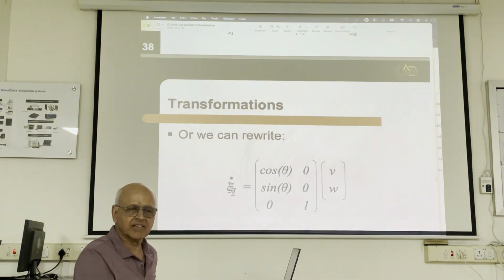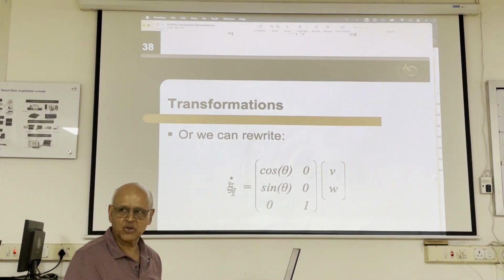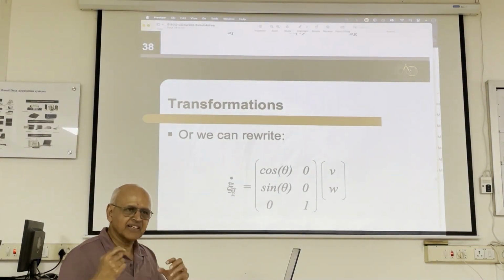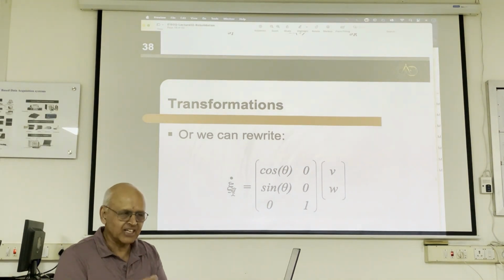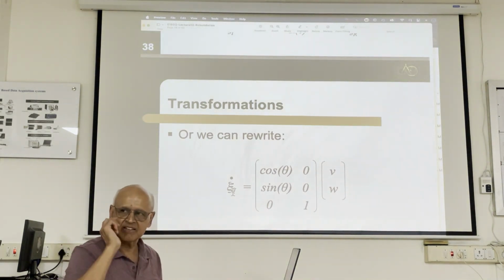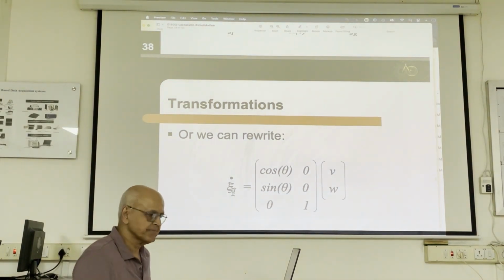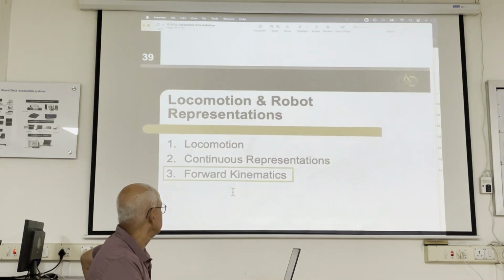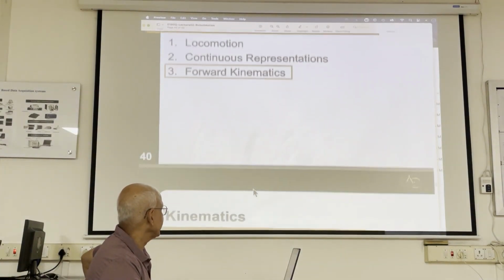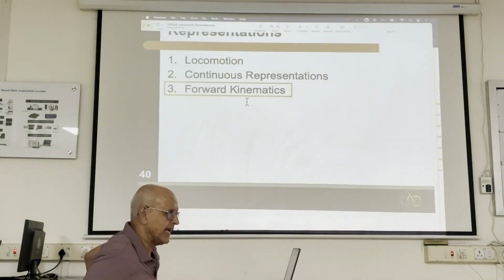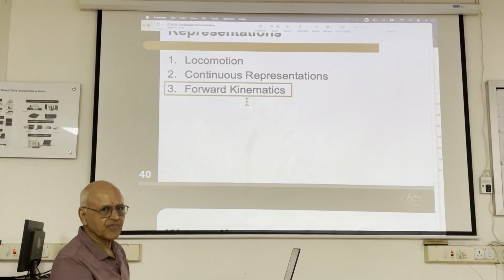So this is the equation that the Gazebo simulator is integrating to tell you where the robot is. If I give V and omega at different points of time, the Gazebo simulator is able to pick up those changes and change the integration, and it keeps putting those circles together. Is that clear? That's how model state figures out where the robot is, it integrates it. So forward kinematics. Now with those equations in place, we can define the forward kinematics of a differentially steered vehicle.